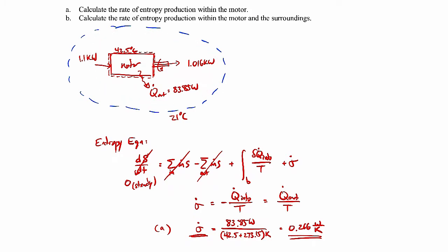The way to think about this is, let's say I have some sunshine, right? And I draw a boundary here. There's a certain amount of energy that passes through that boundary per unit time. If I draw the boundary out here, I would still get that same amount of energy coming out, right? Whatever energy comes out through the first boundary will also be the same energy that goes through the second boundary. So that's the same way to think about this, that whatever heat transfer is occurring through that boundary, it's still going to make its way through this boundary eventually. It's just that at this boundary, the temperature is now different.